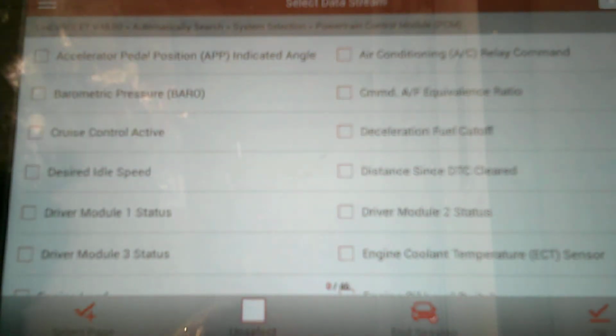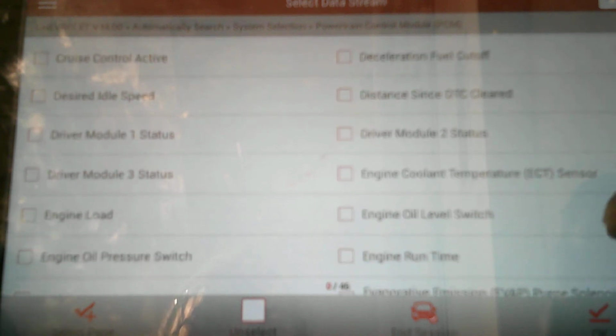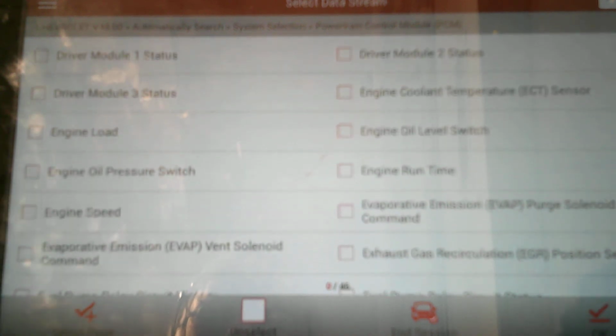We're going to read data stream. We want engine data. And now you're going to see that engine data is separated by groups. Engine, air, exhaust gas recirculation valve. These are different systems, and it picks out the data that's pertinent to that. The data you're going to see are called PIDs. So it has PIDs that are related to those particular topics. Now here you have all of your choices of all the different things that are in the car. So it wants engine speed. They're in alphabetical order. So here is engine speed.